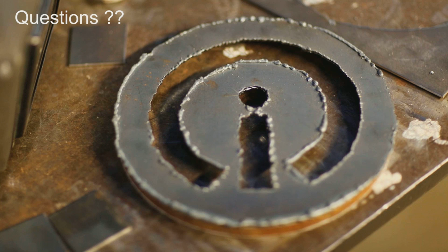In Bluebeam, as you're getting length information, if you have some sort of percentage, say 20% of that's going to be waste, you could certainly build a custom column in there. That's how I would do it. Or you could take that length info out to the quantity link part of that Excel file and put another column in there that says, take this column, multiply it by 0.2. And that kind of takes care of that.